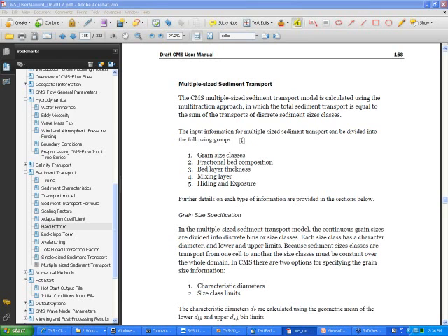Because we use a depth average definition that is weighted by the current velocity, and the OBS is only at certain points in the water column. Okay, so they're not directly comparable. Also, the OBS measurements are instantaneous, and our concentrations are wave averaged. So you need to be careful about comparing those things.